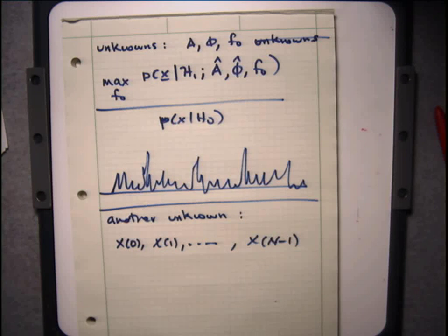Okay? It's entirely possible that the signal that I'm looking for, this sinusoid, wasn't there the whole time. So suppose that for the first 90,000 samples, there was nothing. And then between 90,000 and 95,000, there was a signal. The aliens sent us a cosinusoid, right? And then they stopped. Okay? So how do I detect that?